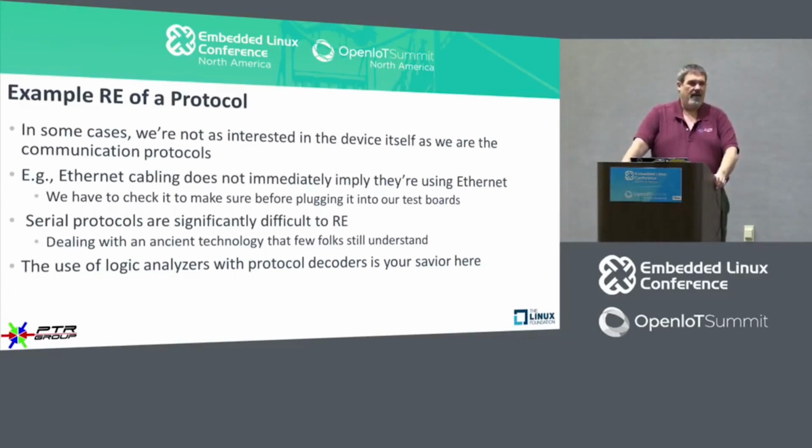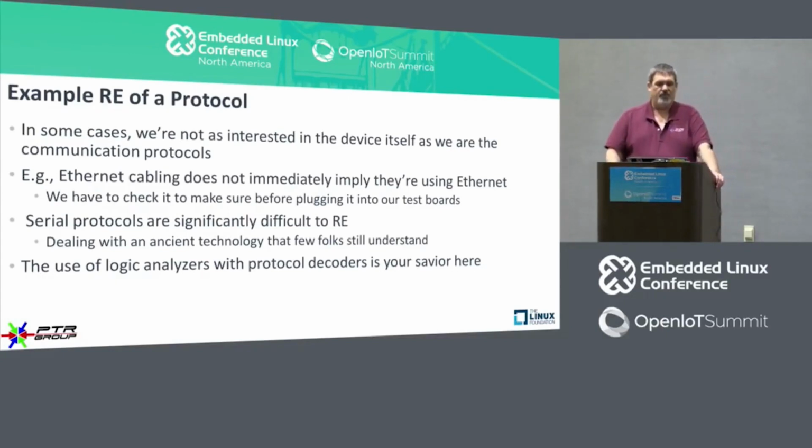But in a lot of this older equipment, we actually have data terminal ready, request to send, clear to send kinds of signals that we need to understand exactly how they work in order to enable the device. Otherwise, it won't work. Now, the use of logic analyzers with protocol decoders is your savior here.